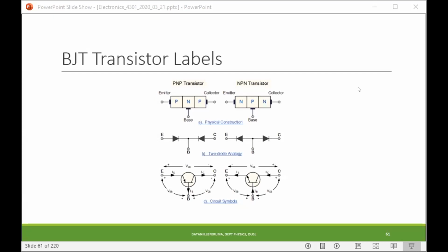And whenever you have the letter V, that stands for volts, the potential. There are two different notations for the potential. If you say something like VB, capital V, capital B, that means the base voltage. Now remember, voltage is a potential difference, so it needs to be measured with reference to some other point.